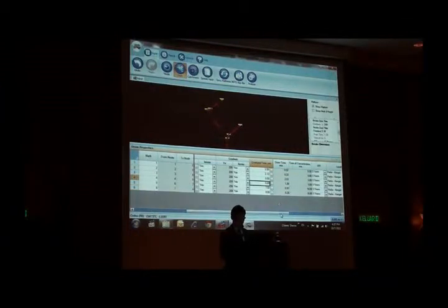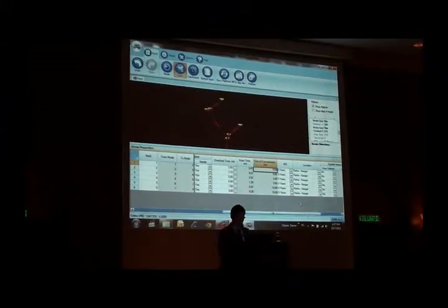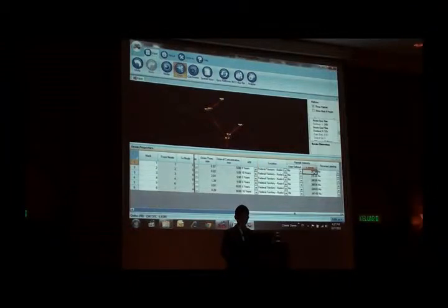After we key in, automatically we'll get the TC. TD, the drain time, is automatically calculated, and TC is T0 plus TD. We follow the MASMA table: 5, 10, and 15 minutes, so we won't give you 6 minutes. For ARI here, let's say for covered I choose 10 years, the rest I choose 5 years. Then for the location, you can choose KL. Then the rainfall intensity is ready, all done.